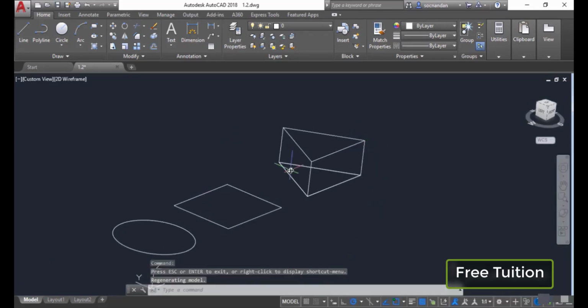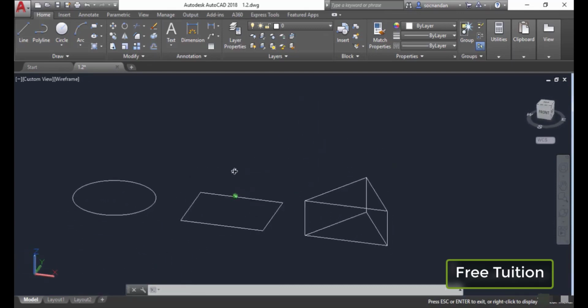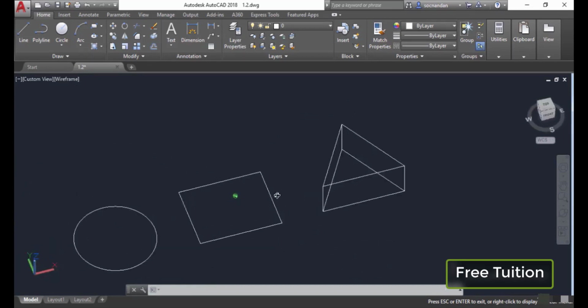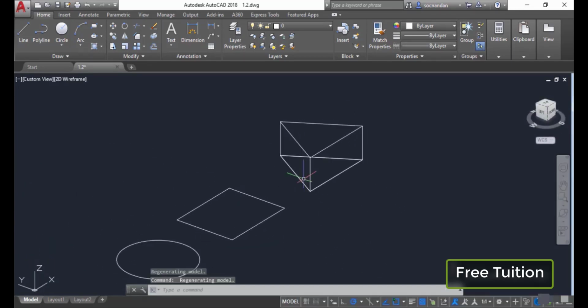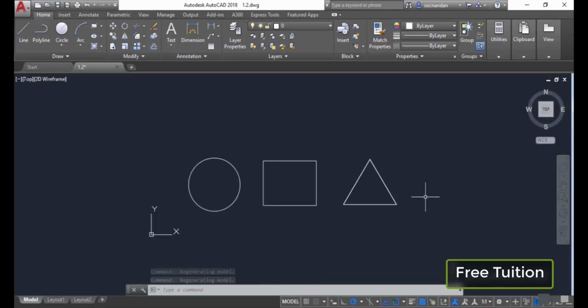Let's press the escape key, and now if you want to access the same tool using the mouse, you can do that as well. Simply press and hold the shift key, then press the mouse wheel, and now instead of pan, that will convert it into this orbit tool, and now you can orbit the drawing in free space. In order to return back to the original condition, simply click on the top of this view cube. And here we have it, the default configuration. Although the angle is not correct, that we can also correct using this small arrow here. So in this way we can navigate in our AutoCAD drawings.